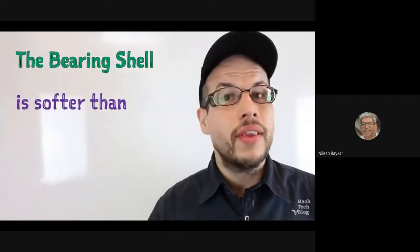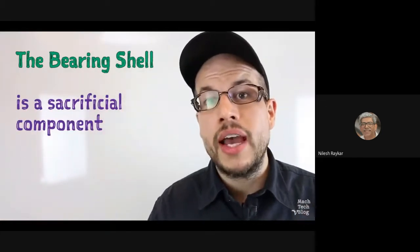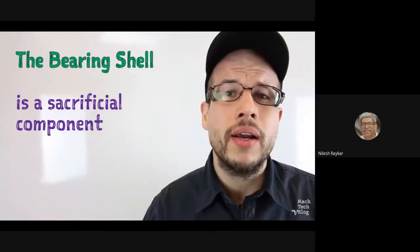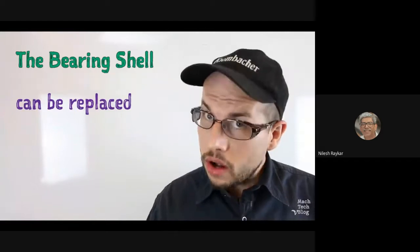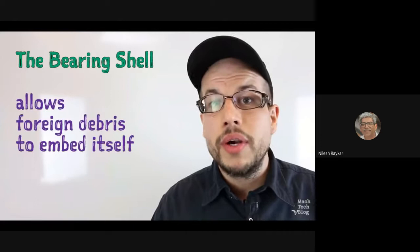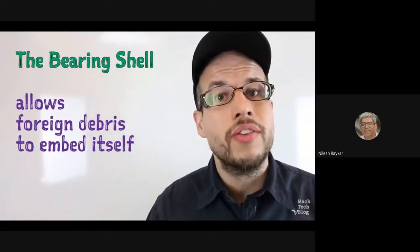But why is the bearing shell made of a softer material than the journal? Well, it's a sacrificial component meant to protect the shaft. If there's ever metal-to-metal contact between the sliding surfaces in the bearing, then the bearing shell will wear before the shaft, and then it can just be renewed or replaced whenever necessary. It's always cheaper to reline the bearing than it is to replace the shaft. And another way that the soft bearing material protects the shaft is by allowing foreign debris or contaminants in the lubricant to embed themselves in the bearing shell instead of scoring the shaft.